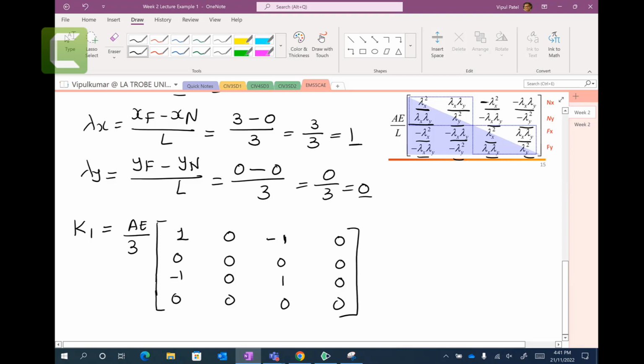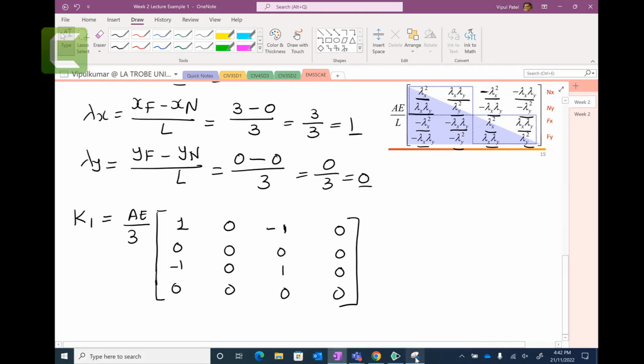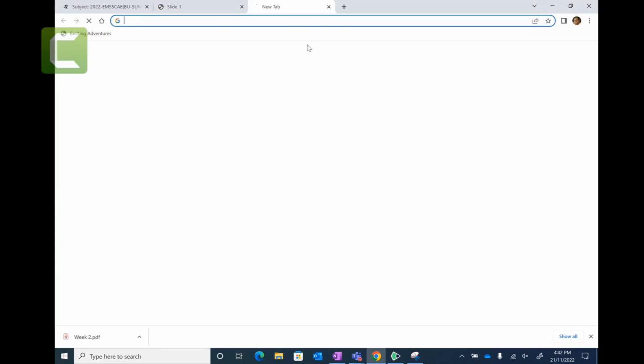Okay. Stop here and I will tell you, what if we don't have a uniform CSA over the length? CSA means cross-section area. You will always get uniform cross sections. Look, let me explain. It is very expensive to build a truss which has a non-uniform section. If you are a structural engineer and someone says you have seen the roof truss, let me search. Thanks for the questions. You always get these.